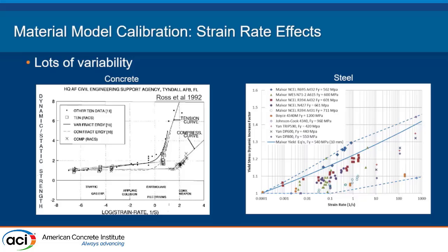Strain rate effects can be pretty important. I think in concrete especially, this is where experience comes in. At very high rates, it's more of an inertial effect, and you don't actually put the dynamic impact factors on top of what the strength already is. It's like a localized confining pressure kind of response. So if you hit it really fast, locally it confines, and that's where your dynamic impact factor comes from. You don't need to add these.